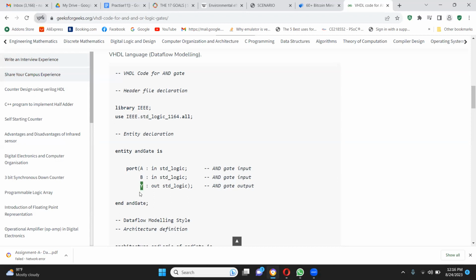Probably then input std_logic. Sorry. And then there will be a Q. Yeah, a D, and then a clock, and then just input std_logic. That's fine. And then only two inputs for D flip-flop? Yeah, there's two inputs for D flip-flop. There's one input for D, and then there is also another input actually. I think you know about it.